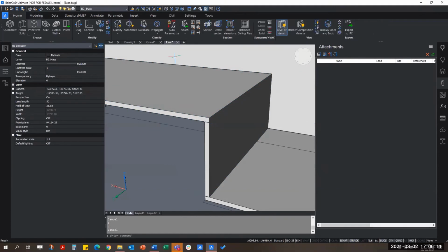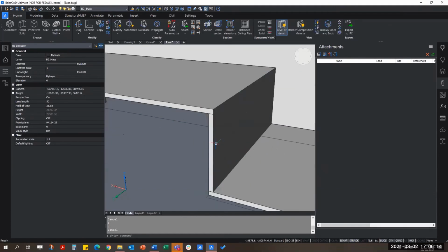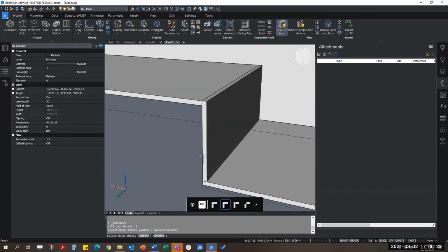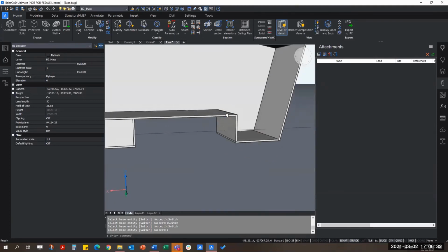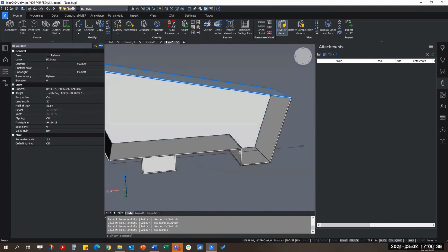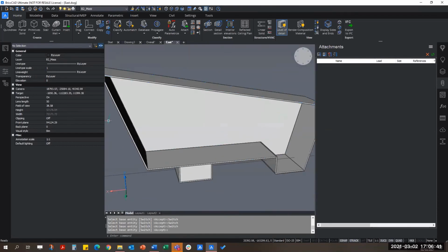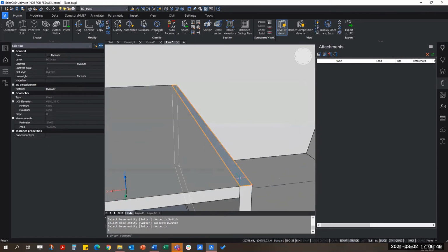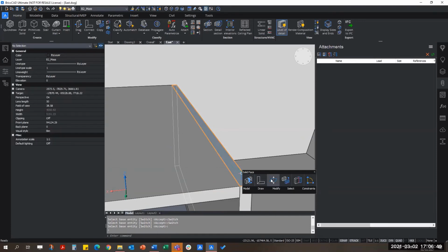The L-Connect tool that I just demonstrated over here on the vertical joint can also be done on a horizontal one like this. So if I do L-Connect, again, I'll toggle to the one that I'm happy of, or even disjoin it. But let's take this one, because I am thinking of bringing this floor plate upwards, but I need a wall to hold the floor plate on this side and this side. So in this case, I could, again, select the space. I could do a push-pull.